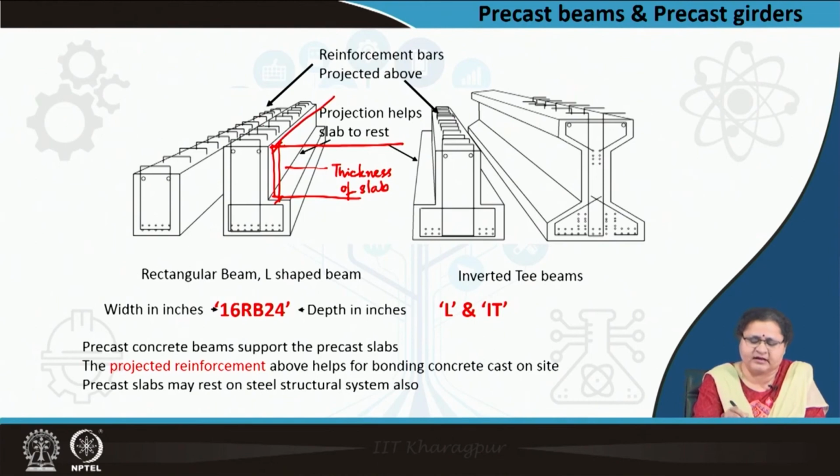So, in this area another slab will come on the other side. These are to be sealed with mortar, and the same level will be reached and the load sharing will take place.